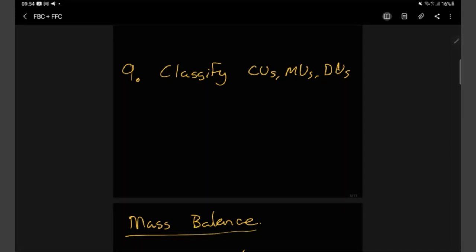And then finally, disturbance variables. These are obviously things that we can't just specify. We have to kind of know where they come from and what they are. So in the sense where you are in charge of a specific section of a plant, a lot of your disturbance variables will most definitely come from upstream processes, and not necessarily only upstream processes.